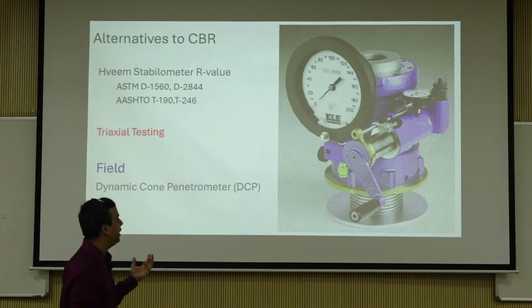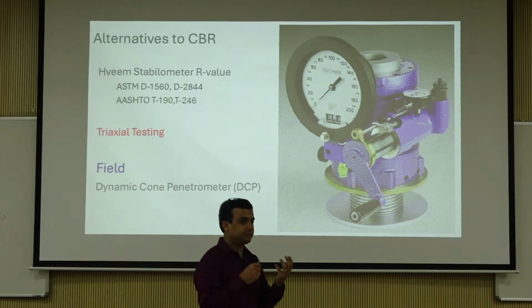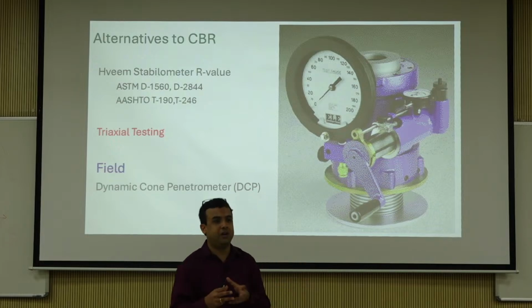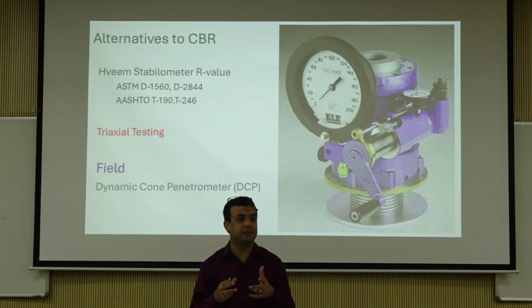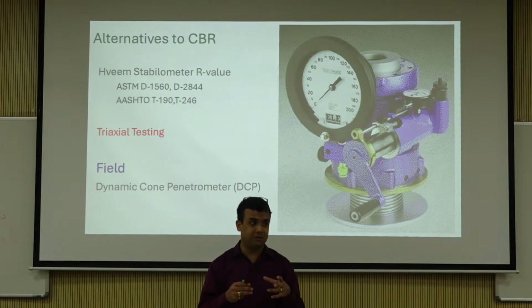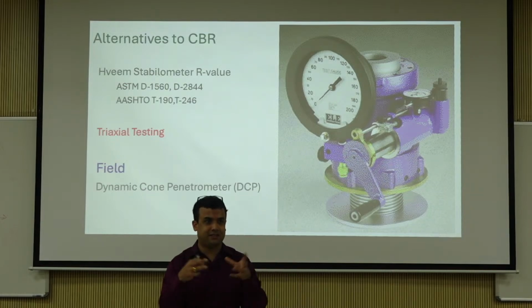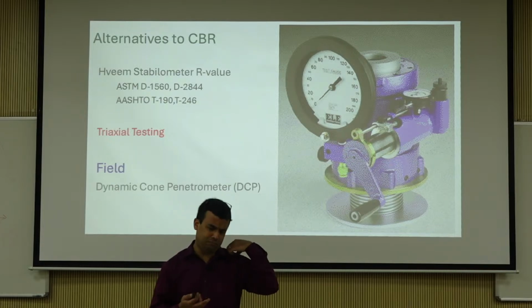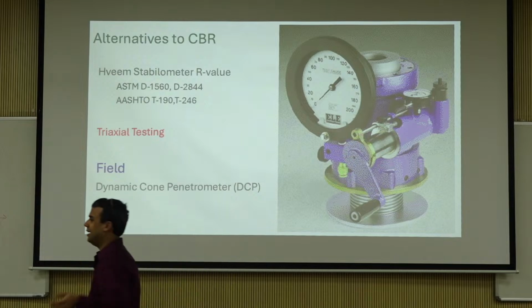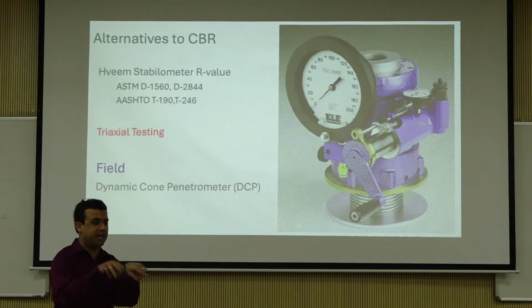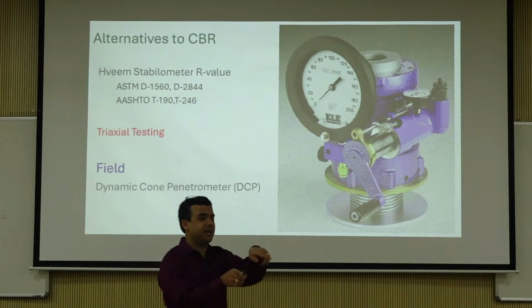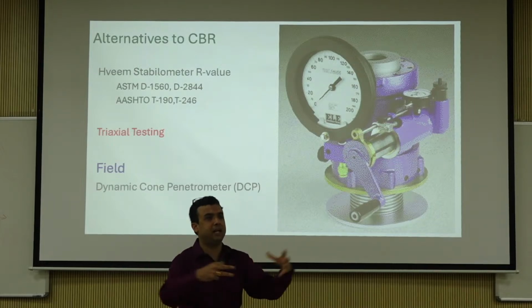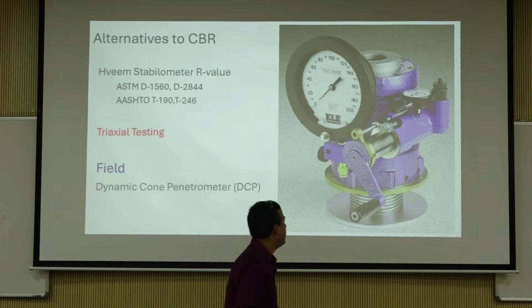The whole idea is related to Poisson's effect. What is Poisson's effect? Say again? That's Poisson's ratio, minus epsilon 3 over epsilon 1. What's Poisson's effect? Yeah, exactly. I would not say x and y because I can always put x and y in the same plane. But yes, longitudinal axial compression will lead to radial expansion.